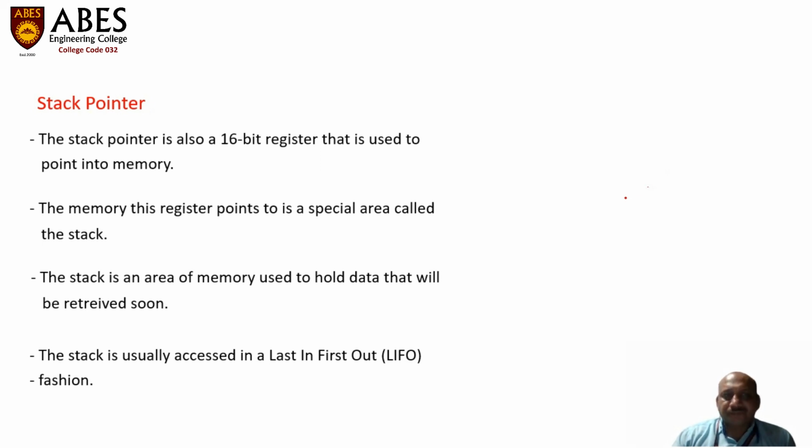For example, if you want to do programming to call some function, then in order to return back to the main program, the return address will be stored in the stack, and the starting address of this stack will be stored in the stack pointer. In short form, it is indicated by SP. So whenever we call a function, the return address will be stored in a stack, and the starting address of the stack will be stored in the stack pointer.